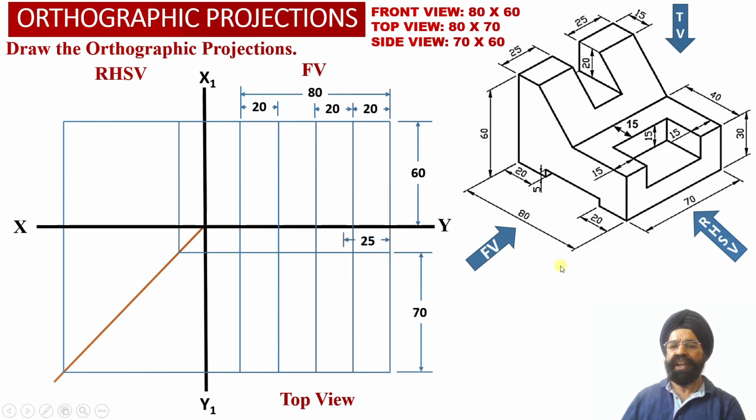Now we also know that corresponding to this horizontal web at the top surface, there is a rectangular slot which is available towards the right hand side view face of the solid over here, and this width we know is equal to 40 millimeter, and we know that there is a web over here which is having a uniform thickness of 15 millimeter.